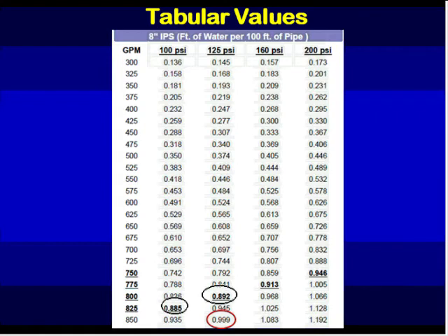These values are the flow rates for this type of pipe where the pipeline velocity is 5 feet per second or greater. So these are the design maximum flow rates, if you will, if you do the design based upon the 5 feet per second criteria.